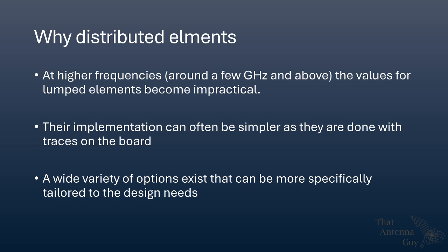Today we'll be looking at distributed elements, specifically for low pass design, and we'll be looking at one specific design, the stepped impedance filter. So why do we use distributed elements? At higher frequencies, around a few gigahertz and above, the values for lumped elements start to become impractical as they become too small to actually realize, and at the same time, the physical length of the circuit starts to approach a point where it can be electrically large and still inside the form factor that we'd like as the frequency gets high enough.